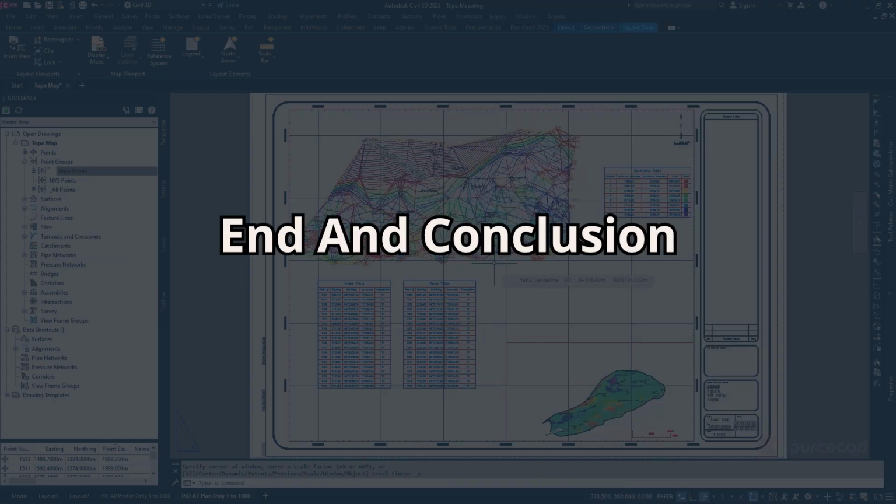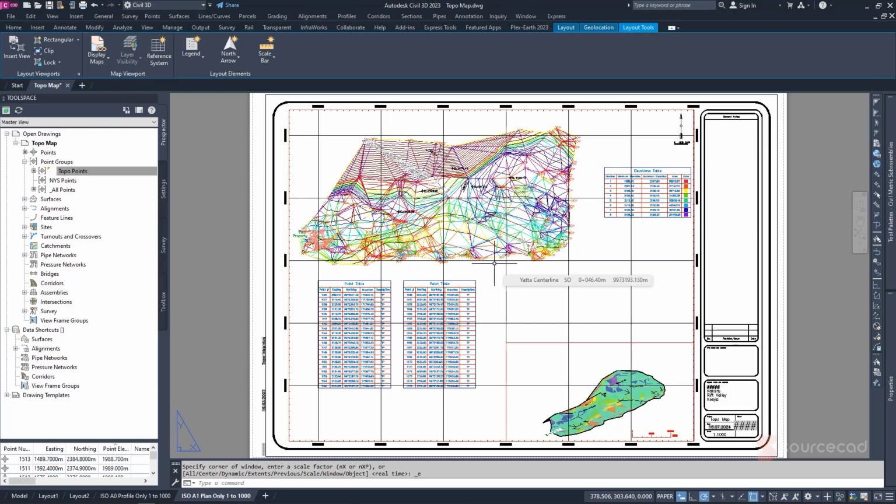So that being said, we are going to wrap up. I've taken you through how to troubleshoot in the event that you have some errors. Make sure you always check your UTM zone, which is very sensitive. Once you have your data correct, all this other information will be seamless.